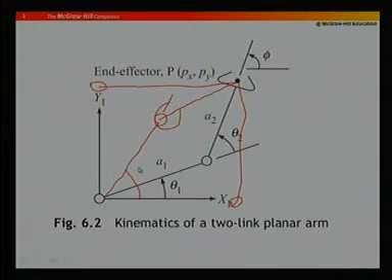In this case, it has 2 solutions, and inverse kinematics is required for control purposes, because just now I told you for control purposes we are habituated in providing Cartesian coordinates. So, we will ask the robot to go to Px, Py, and the controller will calculate what will be theta 1, theta 2. Of course, the controller is programmed by roboticists like me and you. So, then you have to decide in the program which theta 1, theta 2 you would ask the robot to go, this theta 1, theta 2 combination or this theta 1, theta 2 combination.